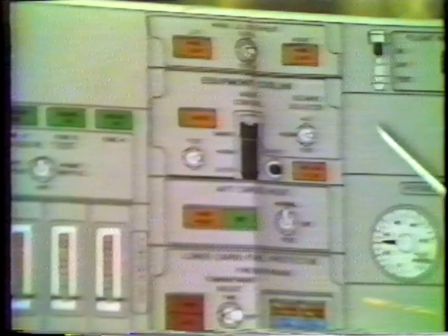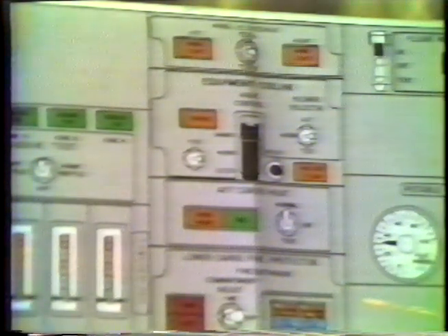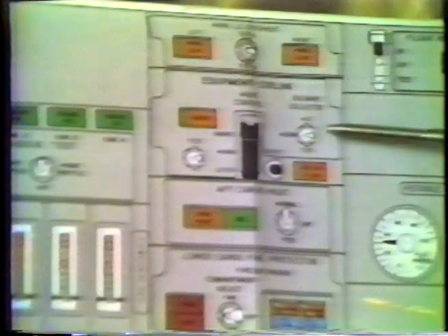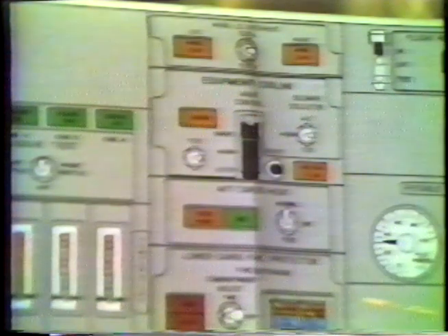The no airflow light may or may not come on with the smoke light. They're independent of each other. The no airflow light indicates that the electronic cooling blower is not pulling sufficient air across the equipment to keep it properly cooled. We have 2 blowers. The blowers are operating under all aircraft power operation, and which blower you're operating is selected by the switch right here, a normal position or the alternate position. In the test position, you take power away from the blower and the blower stops.